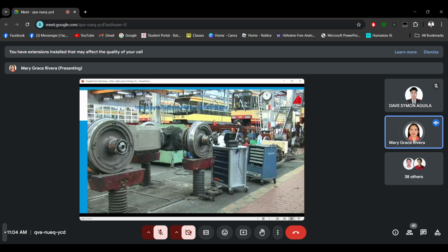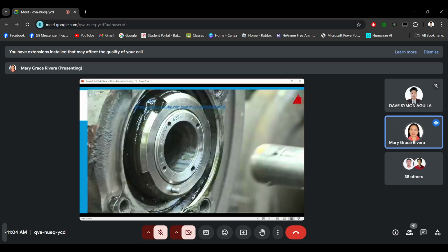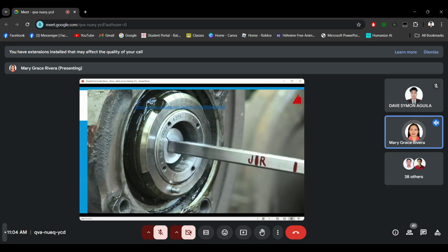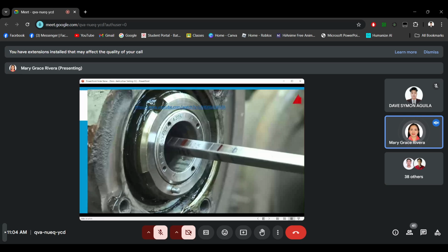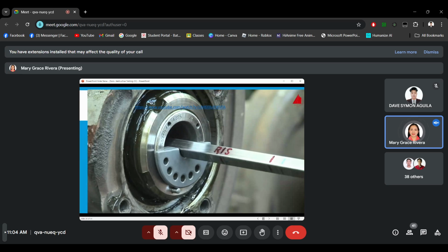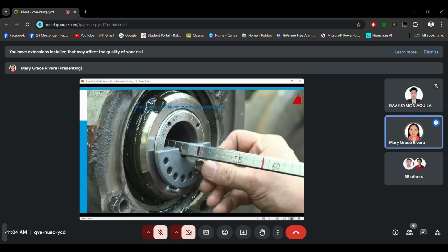Now he takes a special probe designed exactly for this purpose, inserts it carefully into the bore with a mount, and evenly spreads out the couplant by turning and pushing. He has accurately marked the most important examination points at the mount.